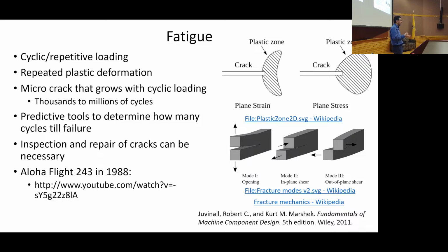When I say takeoff and landing, yes, Frank. But the inside is pressurized, so when it goes up in the atmosphere where there's less pressure, the fuselage wants to expand. I'm not talking about landing gear here, I'm talking about the fuselage. Of course, the landing gear is also going to experience more loading, but that's a different thing altogether. The fuselage itself is going to be expanding and contracting every time you take off and you land.